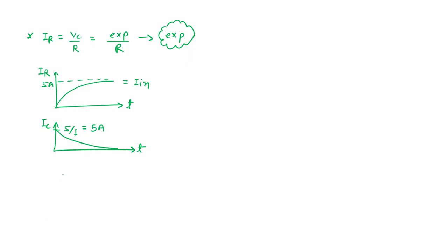Okay, and what is my capacitor voltage? Also the resistor voltage, it also is the output voltage. VC is also the VR, is also my V out. It is nothing but the exponential reaching the final value of 5R, which is here 5 volt, because I am considering R to be 1 ohm. Okay, so this is the sort of discussion regarding that question.